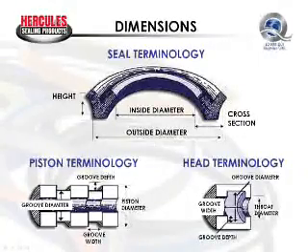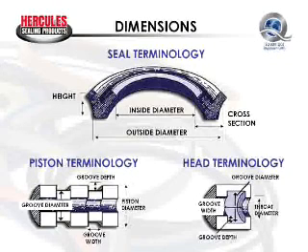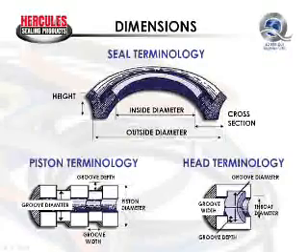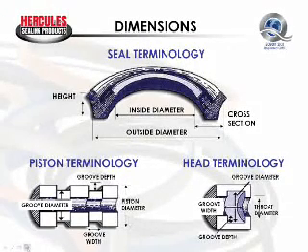That's important because it's going to relate to the groove depth in our cylinder, but also because most suppliers' catalogs for O-rings and other seals are organized by cross-section. They generally start with the narrowest cross-section, 1/8 of an inch, and work up through the various cross-sections, and within each cross-section, seals are organized by inside diameter. So it makes it easier to find a particular seal that you might need to use.